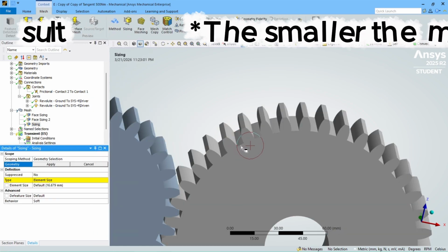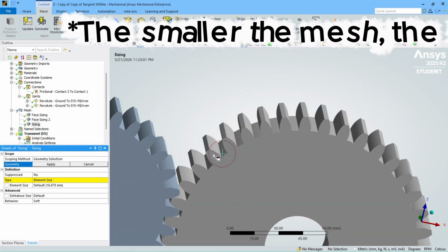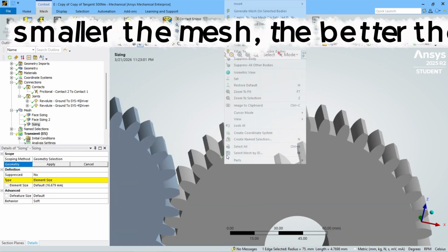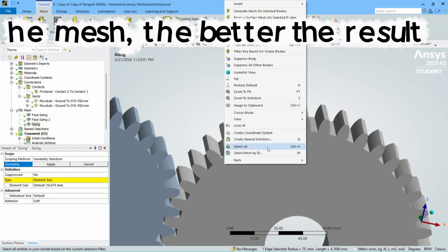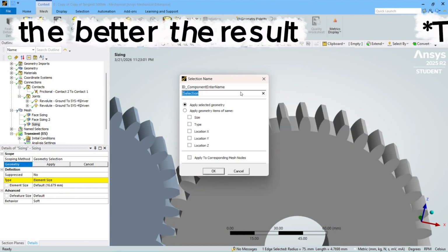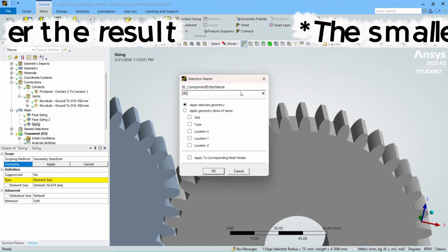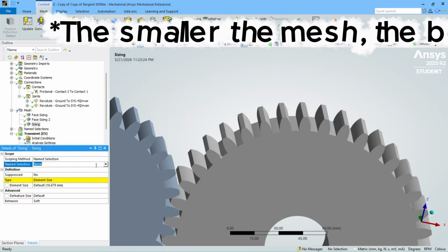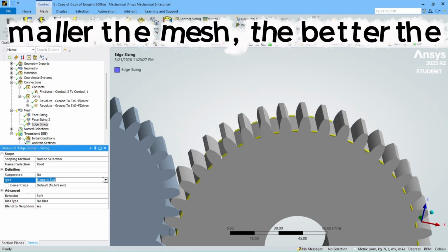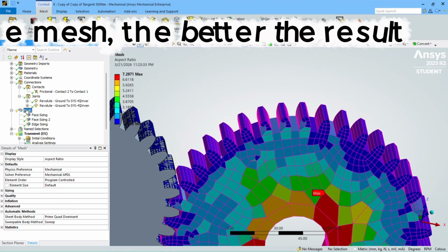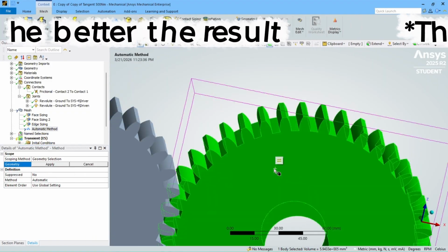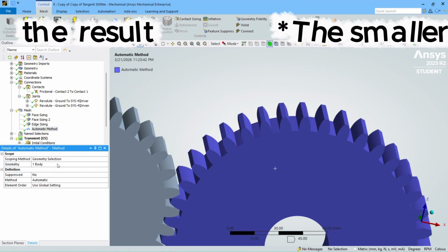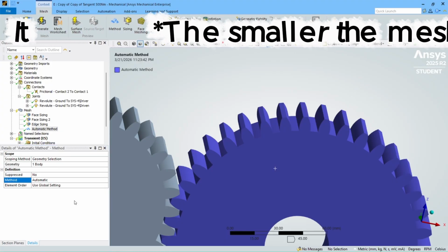You can also make a new named section in ANSYS Mechanical by clicking the line or faces. Create named section. Use sizing mesh on the root. Type sizing mesh by number of divisions. Use multi-zone mesh on the driven gear to make the mesh elements have a structured shape.